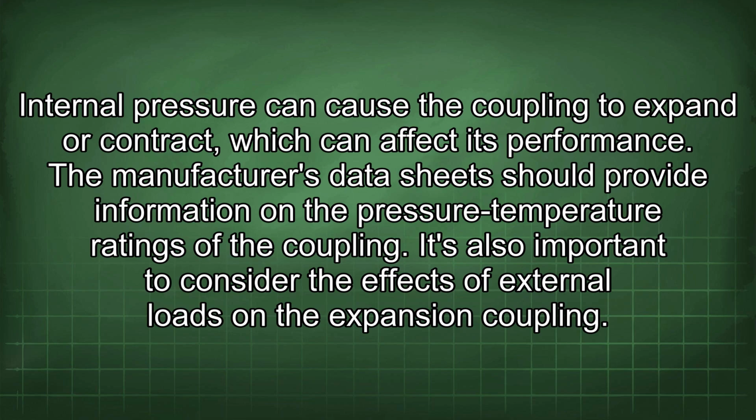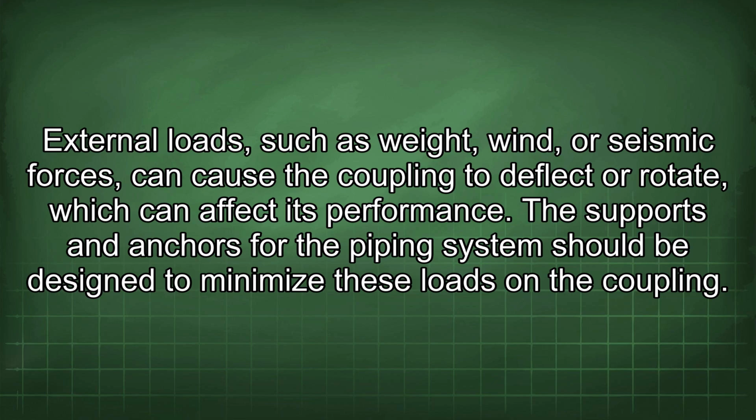It's also important to consider the effects of external loads on the expansion coupling. External loads, such as weight, wind, or seismic forces, can cause the coupling to deflect or rotate, which can affect its performance. The supports and anchors for the piping system should be designed to minimize these loads on the coupling.